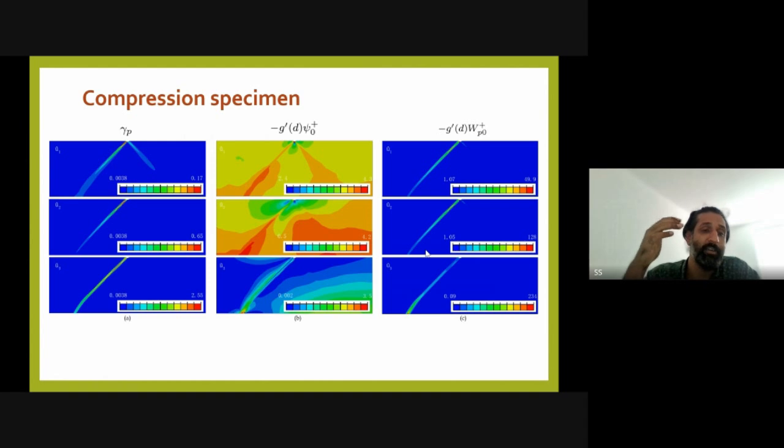The initial yield in compression is much greater than the initial yield in tension, and the difference between the initial yield and the strength under compression is lower than the difference between the initial yield and the strength under tension. So we will usually see that the compression specimen shows very little non-linearity in its graph, and it will fail in a very brittle manner after a slight stage of plastic deformation.